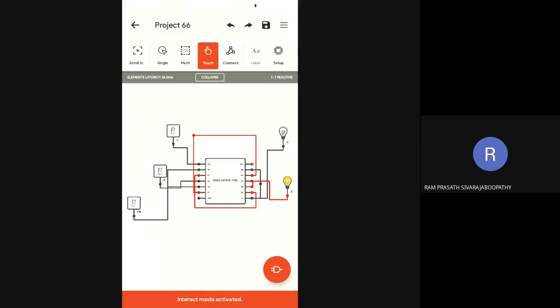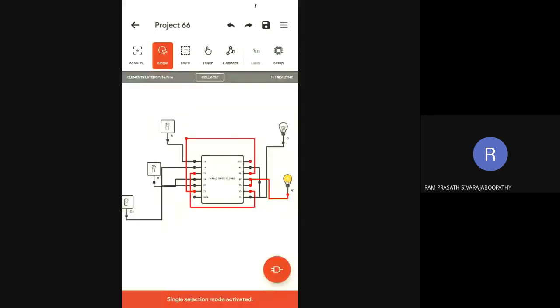If you disable the clock, inputs will not be considered. Whatever input you give, the output does not change. Is it clear now, Srihari? Flip flop, understood? When the clock is high, what happens? The circuit is enabled. When it is low, what happens? It goes into memory state. That's all. So whatever is stored in the flip flop is maintained. That's all about the SR flip flop.